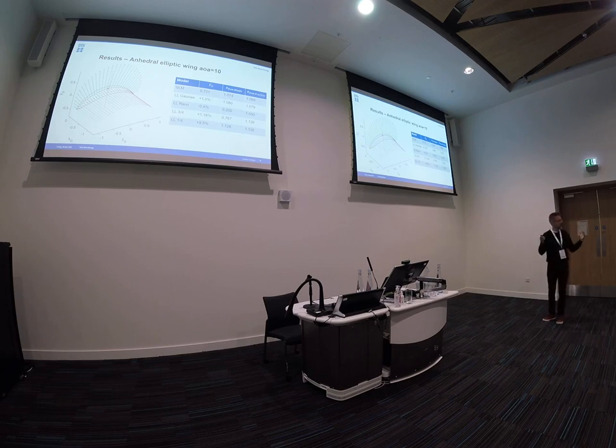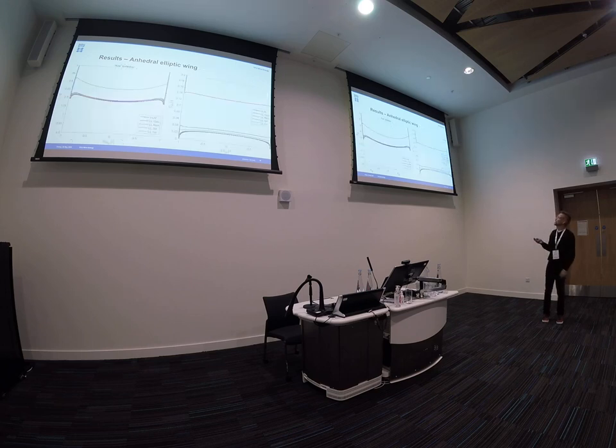Anhedral. Now we bend it like a kite. Then what? Well, this method is still not good. These numbers show that when you evaluate the forces on the blade, we're doing good, and they agree with the numbers from the Trefftz analysis, so we're good. So it's pretty nice. These results still give good results for lift and drag if you use the far-field approach, but if you are not flying straight or doing maneuvers, you can't do that.